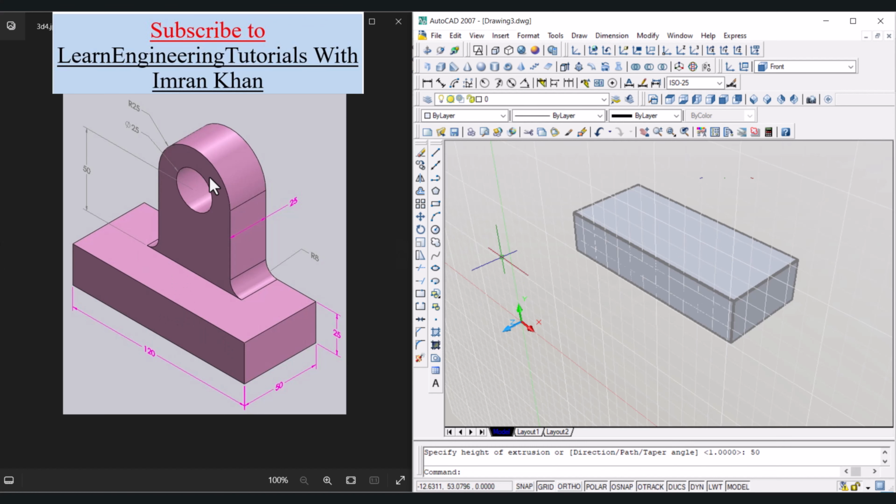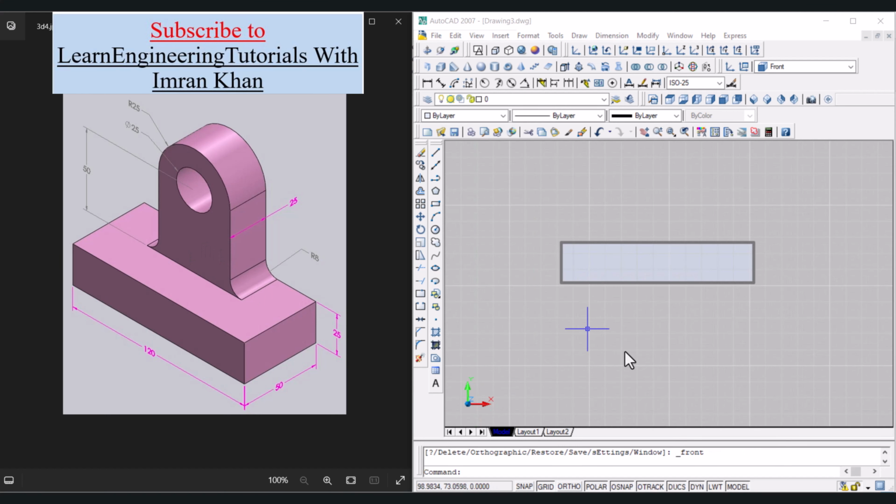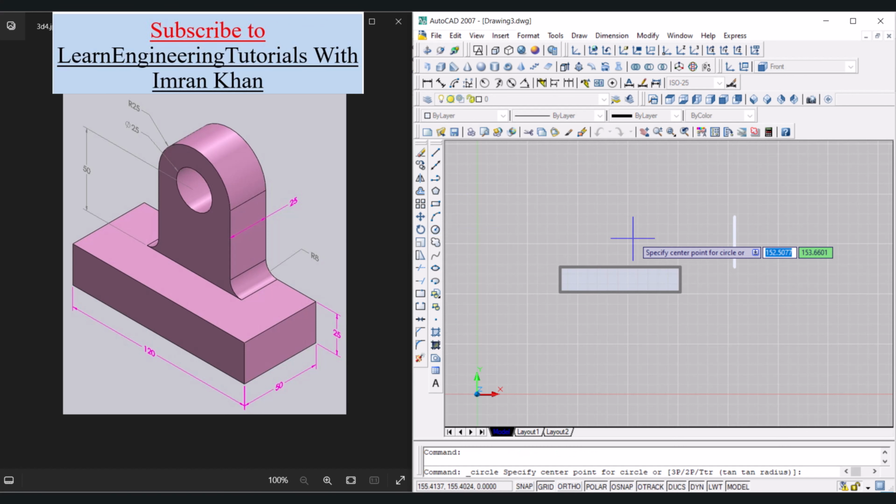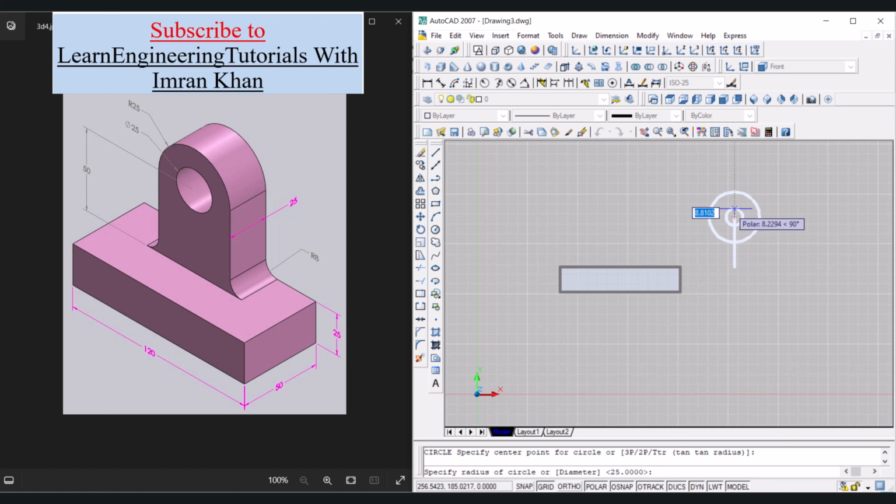Now we have to draw this object which consists of this hole and this object. There is also a fillet involved, and it looks like this object is at the center of this side, right? Now in the front view we have to draw this object, right? So for that let us click on line, click here, move in the upward direction by a distance of 50, enter, press escape, click on circle, bring the cursor over here, click, and this time write the radius of 25, enter, press enter again, click over this endpoint, and this time the diameter should be 25.